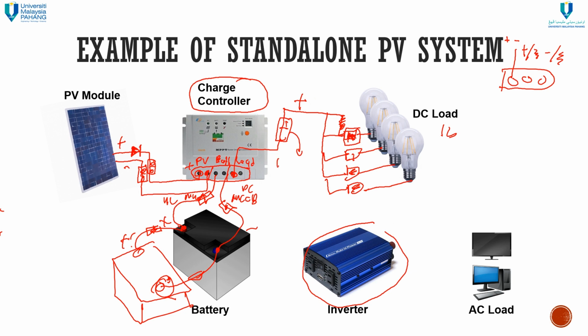One light in the house, AC. So for this MCCB, for example, you put a light in the house 6 amps, 10 amps, like that. Then after that, they're going to have the separate switches, and then the negative one will connect at the back here, and all are parallel also for the negative. But for the plus one, if we want to have a separate switch, you put on each parallel wire cable one switch. Then you can control the loads one by one. Alright.